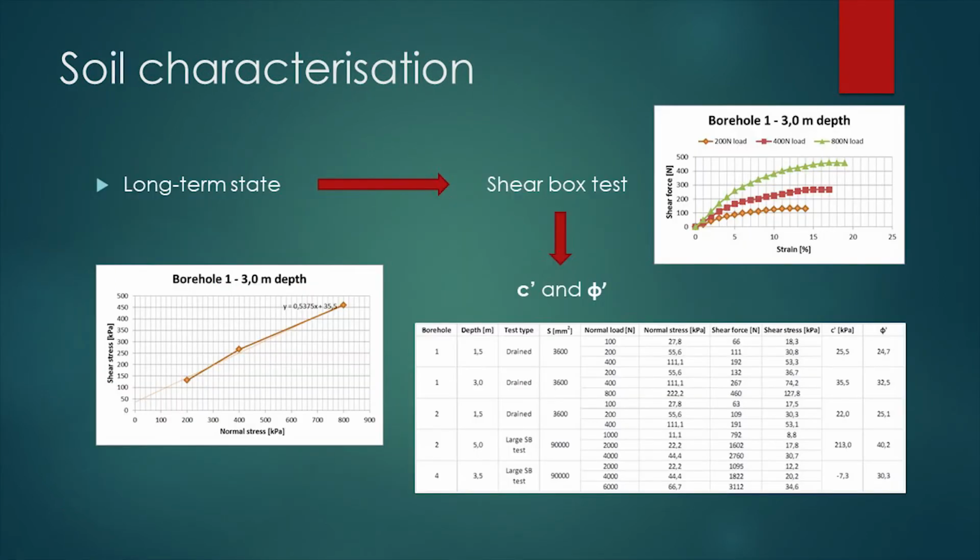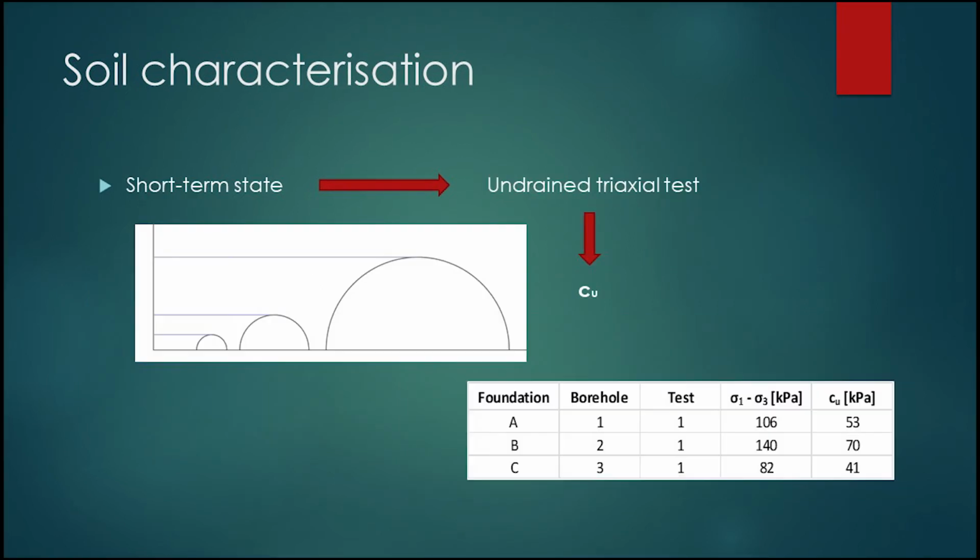We've used the shear box test results in order to find the effective stress parameters of the soil Phi and C. After having confirmed that the soil studied is loose, we've done a summary table with the results and the characteristics of the soil studied. As we had some undrained triaxial test results, we've determined the total stress parameter Cu. With all the parameters we had, the use of Mohr circles was an option, and as we've assumed that the strength envelope for Phi equals to 0, we take Cu as the radius of the circle.